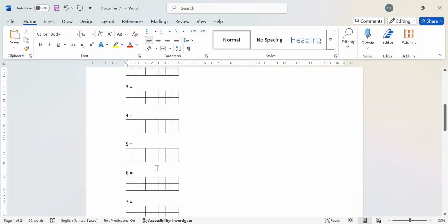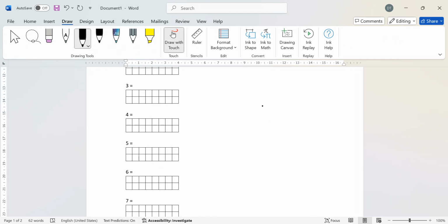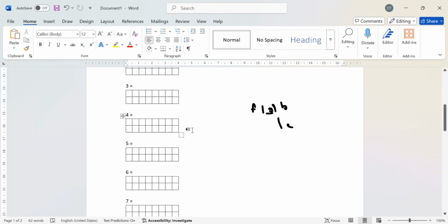But, for example, let's solve for the number 4. Which segments are displayed? B, C, F, G. All right. So A has to be 1, right? B is 0, C is 0, D is 1, E is 1, F is 0, G is 0, and then DP is 1. So 1001, 1001, it's 99 hexadecimal. We don't write 0 here.